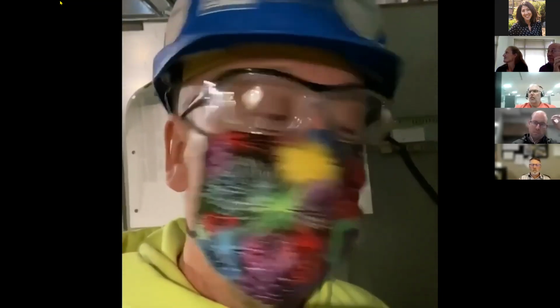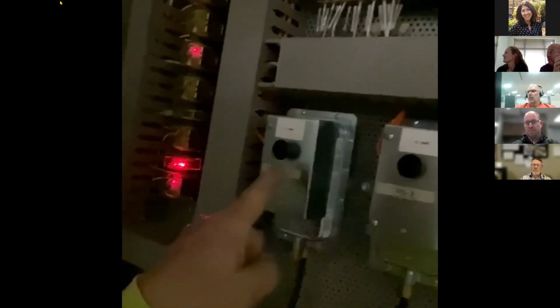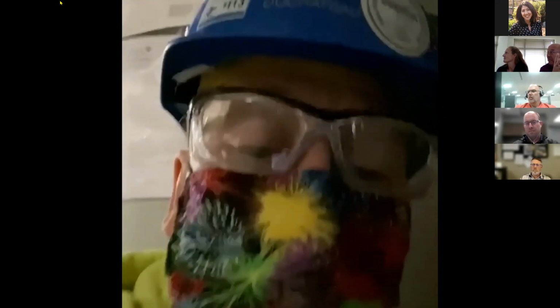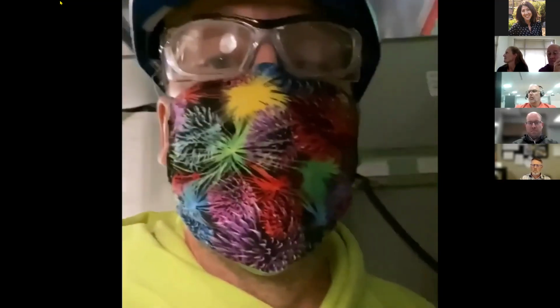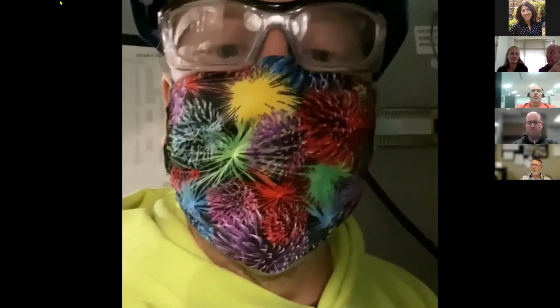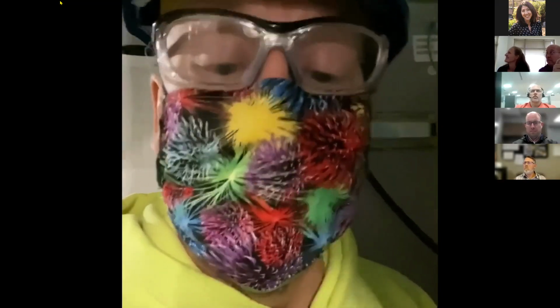So we're going to hit the reset panel, but one thing before I do that, and I had that photograph earlier, we are not big advocates of only labeling the covers, because if anybody ever takes the covers off, how do you know that someone won't put PS1 over here and PS2 over there? And there were no labels on the back. So hitting the reset panel here, and nothing really loud is going to happen here. Oh, there goes a couple relays. And we're off to the races of starting up the unit again.